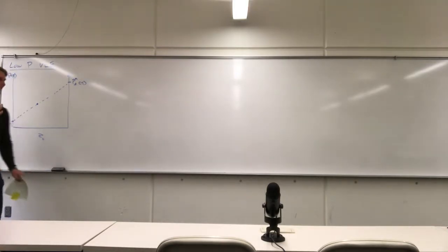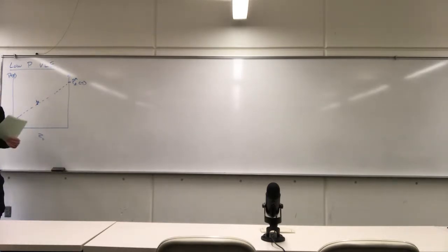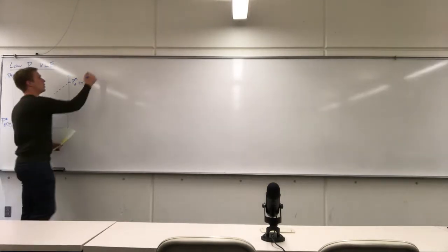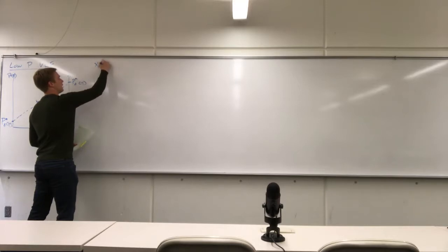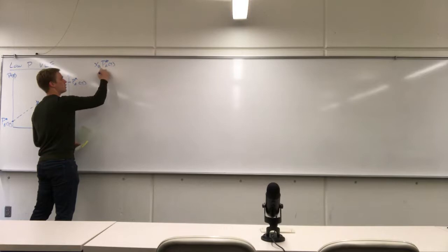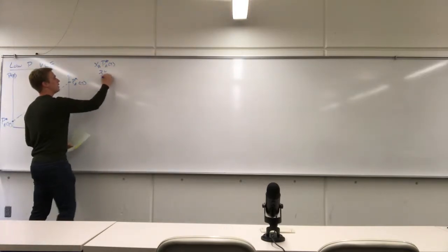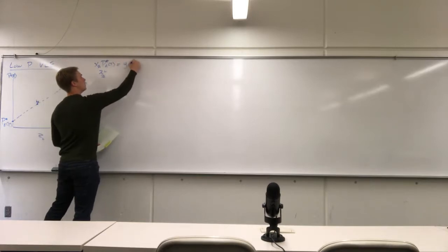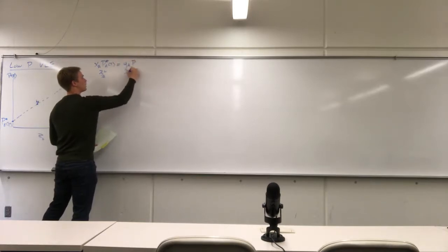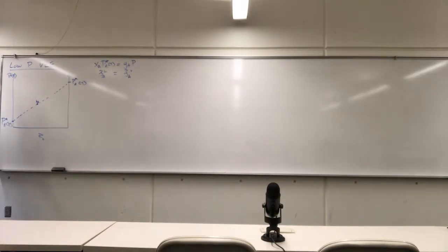The only thing that I need to relate my liquid composition to a vapor composition is that my partial fugacities are equal. So in the simplest case, that's Raoult's law. So in Raoult's law, I want to relate my liquid properties, right? This is my partial fugacity for the liquid phase for species A. I want to relate it to my vapor phase. This is my partial fugacity in the vapor phase. That's the model that we've chosen.